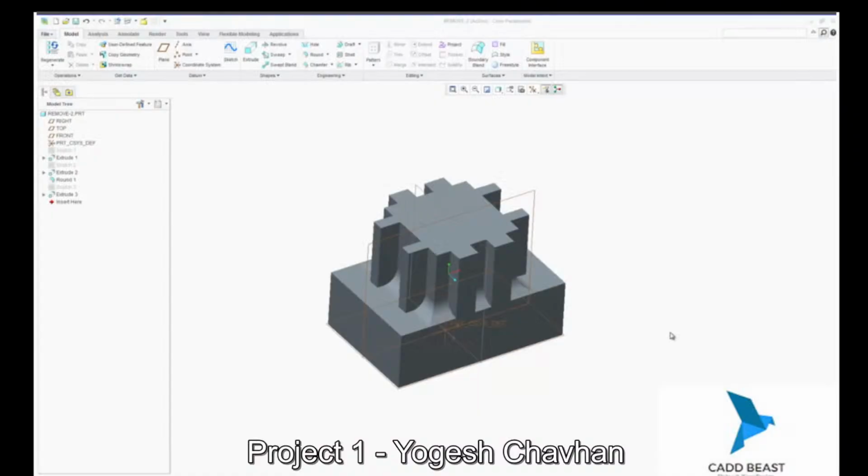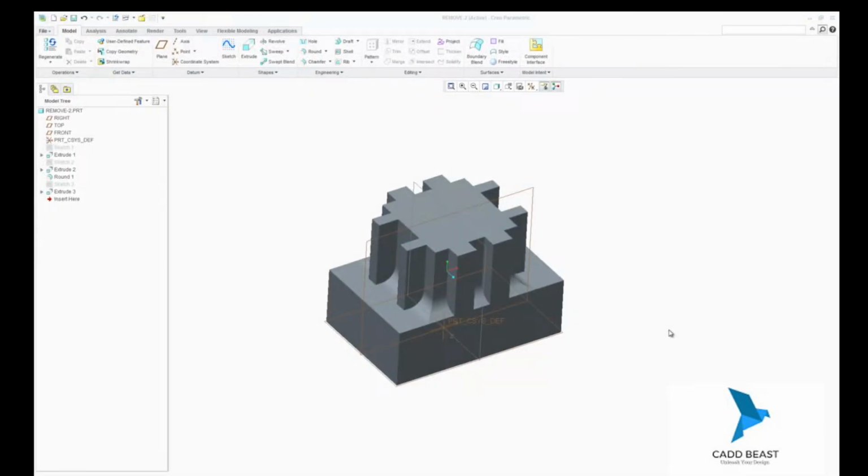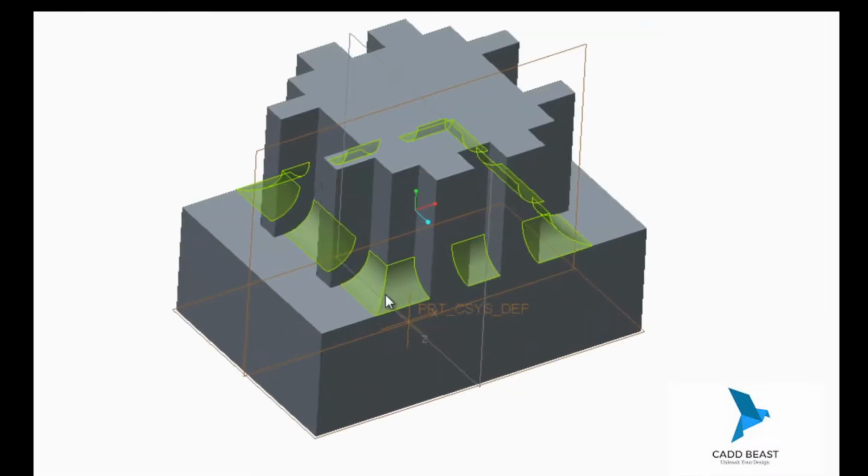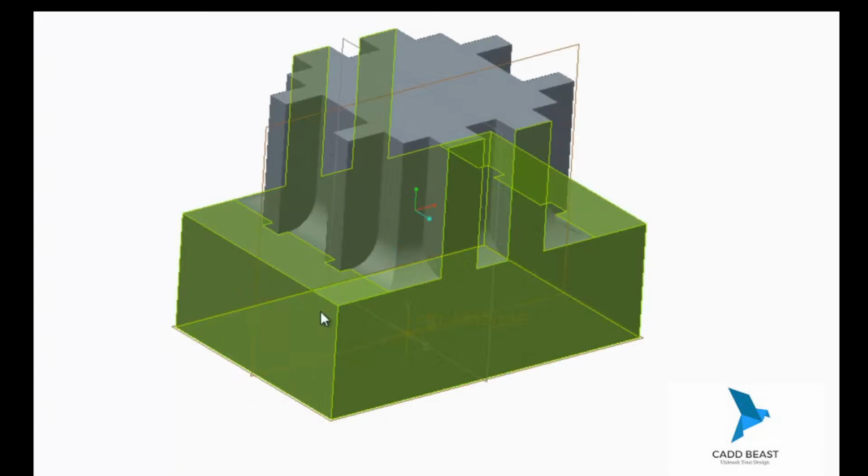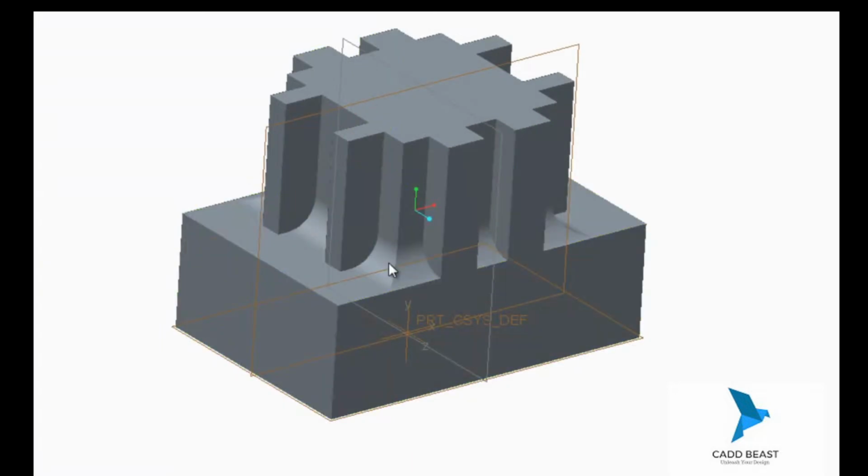This tutorial is for selecting and removing multiple surfaces or gaps for removal. The Remove tool helps you remove geometry without the need to alter feature history or redefine any number of features. For this demonstration, I want to use the Remove feature to remove parts of these rounds. The first step is to select all the rounds.